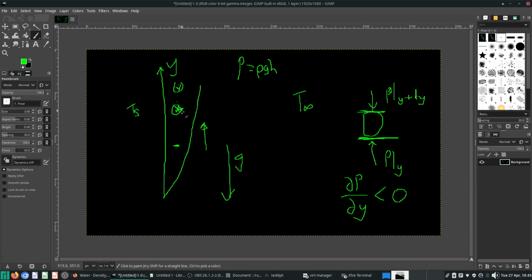You need to integrate all these small pressures on top all the way up, because the density may change, so the pressure on top may change as well. We are not quite sure how this pressure will change from time to time, at least inside the boundary layer. So we can't use the rho GH trick inside the boundary layer. It's not as clear how to do it.